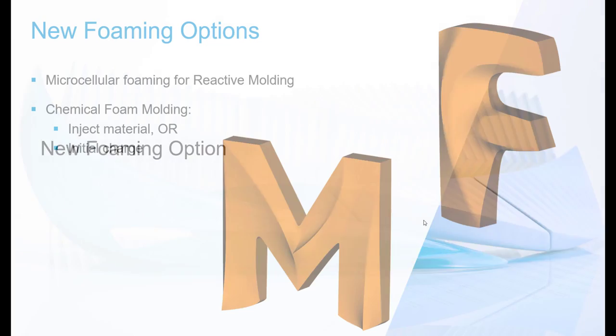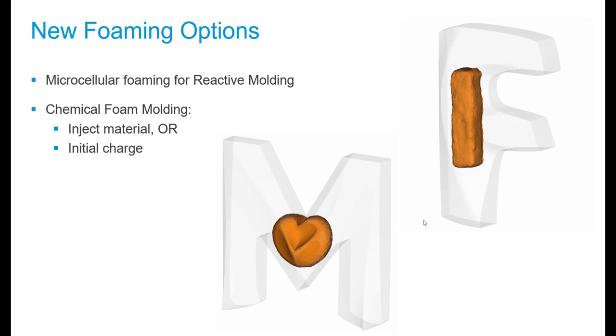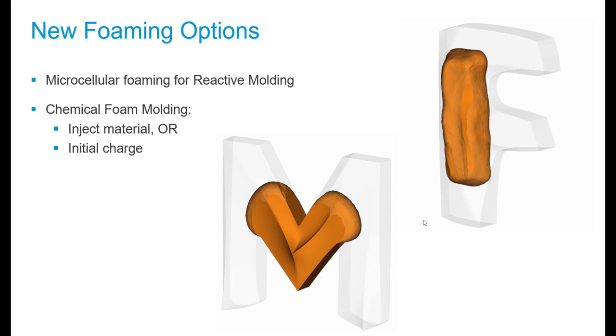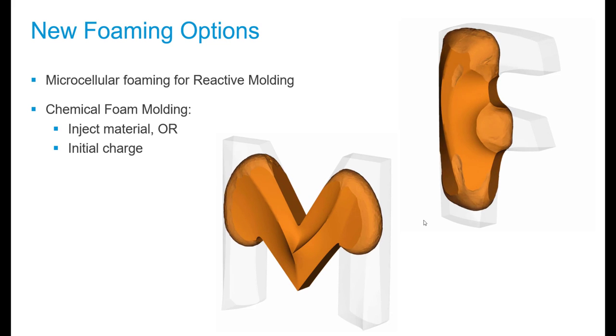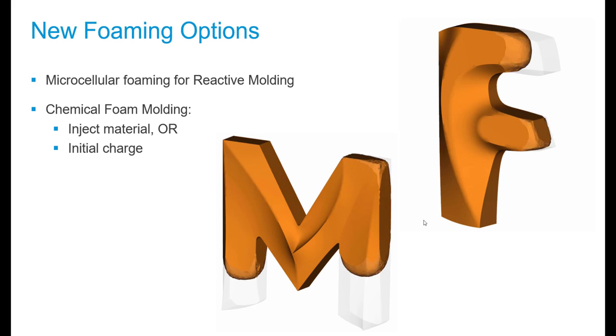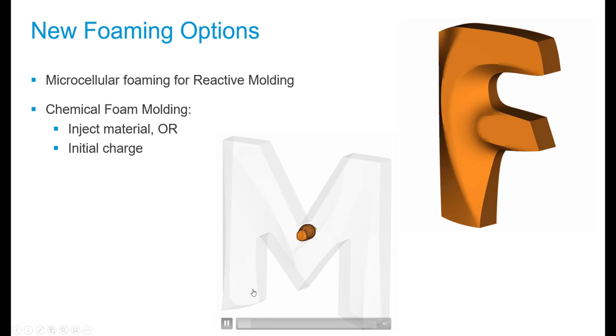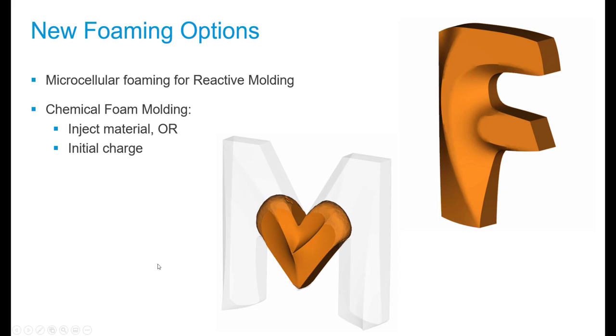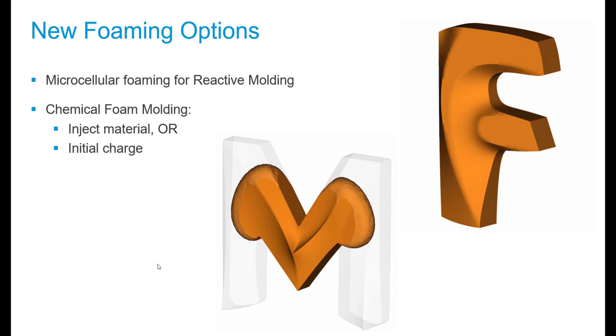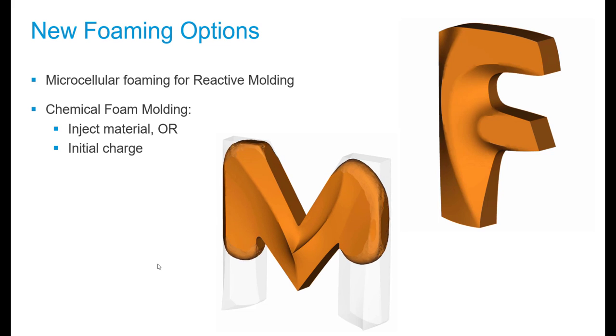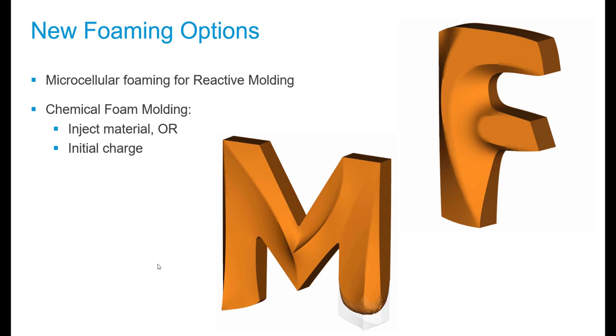As a new option, we brought in the polyurethane foaming analysis, and there are two variations of this represented by these two images. In Moldflow we now have injected foam. We continue to inject the resin, and the resin will expand and foam out the cavity. At some point we'll actually stop injecting, typically around 10% of cavity filling, and the rest will be filled by the foaming action.